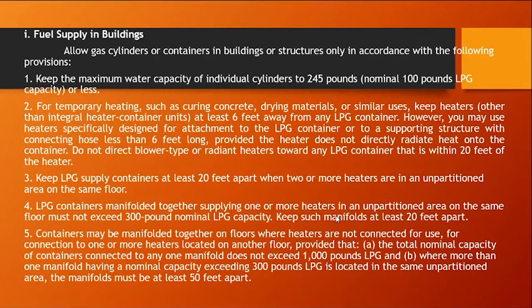So, fuel supply in buildings. Allow LPG cylinders or containers in buildings or structures only in accordance with the following provisions. First, keep the maximum water capacity of the individual cylinders to 245 pounds, nominal 100 pounds LPG capacity or less. For temporary heating, such as curing concrete, drying materials, or similar uses, keep heaters at least 6 feet away from the LPG container.